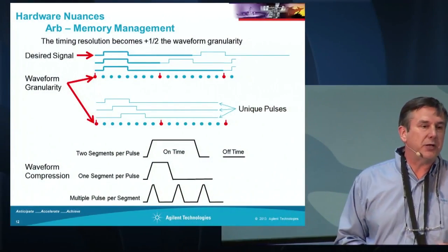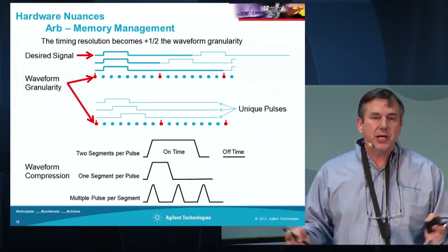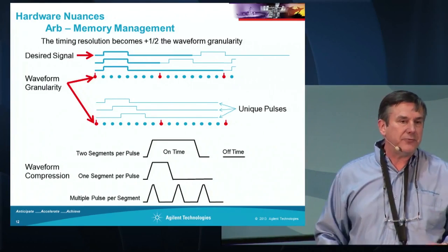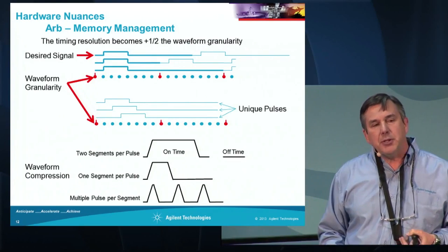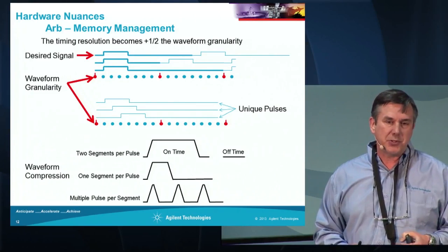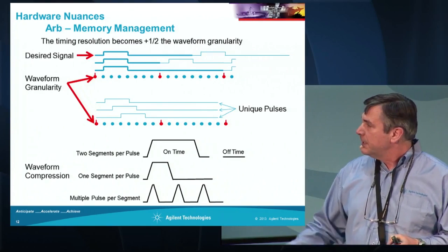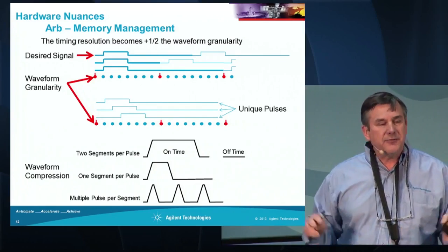As you get down to more and more narrow pulses, perhaps you want to combine those such that they don't exceed the 48 points of the memory block that you have to write for your waveform. So there are methods to account for specific memory blocks within your arbitrary waveform generator. All of this is done automatically for you with Signal Studio for Pulse Building, which is one of our waveform creation software tools.